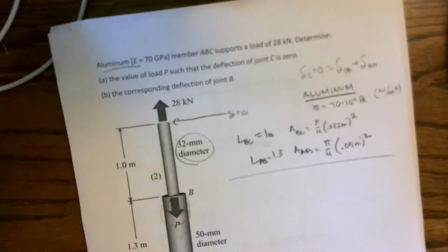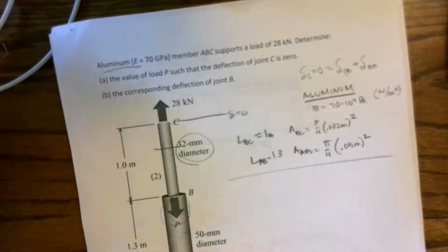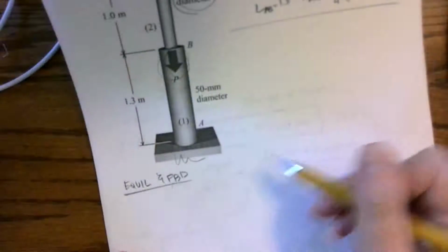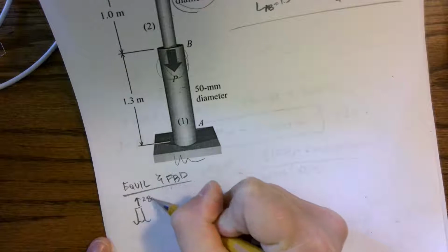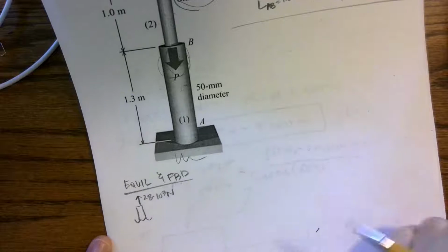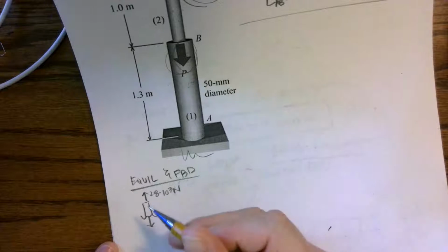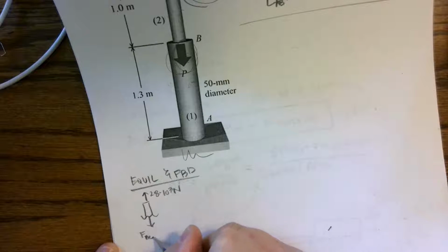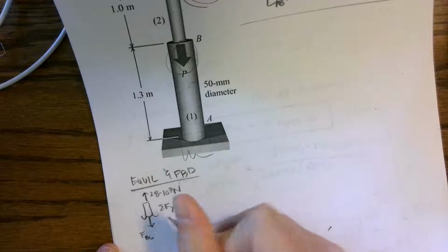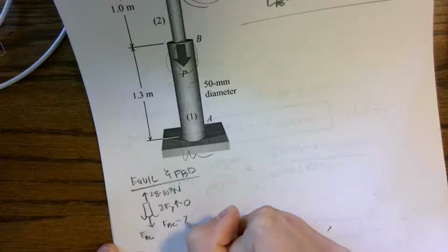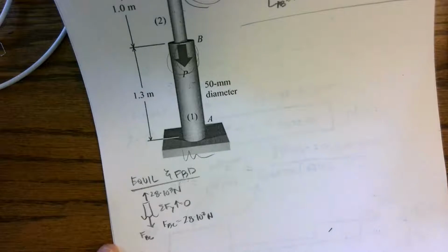So I'm going to take my post-it note, start from the top and come down. I'm going to make a cut. Okay, here's my little segment. I have 28 kilonewtons, which is 28 times 10 to the 3rd newtons, because again, I like to have everything in proper units. I don't have to worry about units when I'm setting this up. So I have the force from B to C. I can sum forces in the y direction equals 0, and I can see that force BC is a positive 28 times 10 to the 3rd newtons. So it is indeed a tension member.